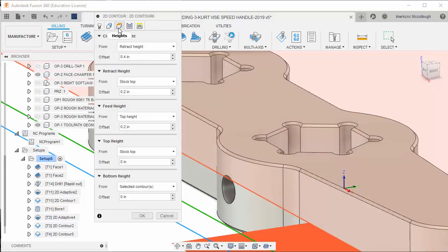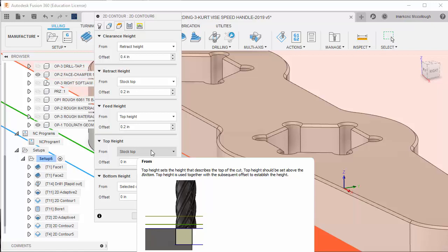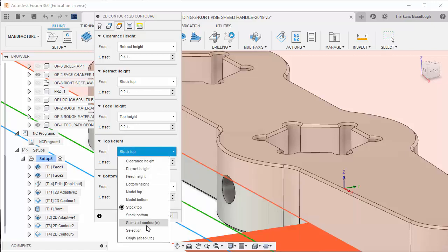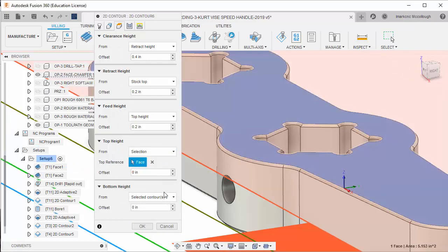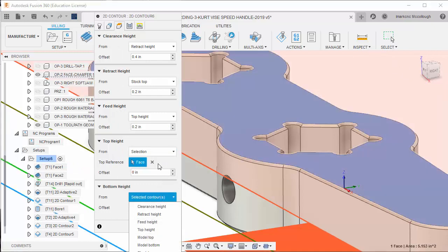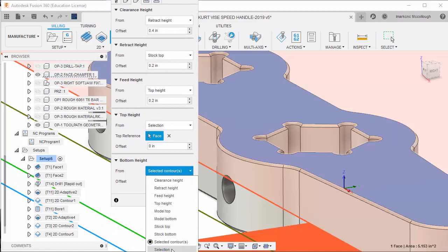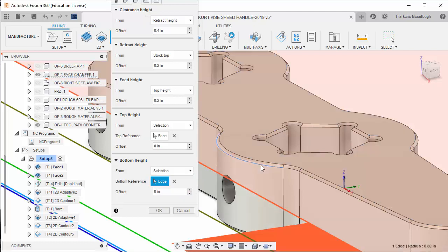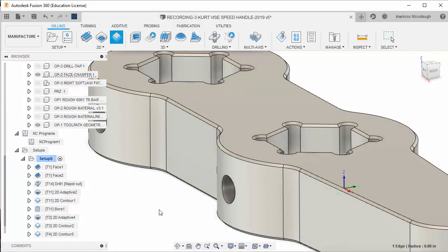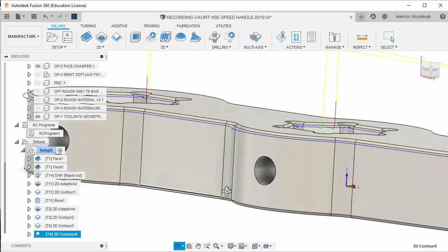From there, the same idea is our height again. Since this is a different level, it's not the same level because they're all cut different in the jaws and where they're positioned, I'm going to choose the selection, grab the model. I'm going to choose my contour selection. Let me move that up a little bit. And I'm going to choose the selection again down here, and I'm going to choose it to there. I'm going to add a -10 thousandths to that one too. And again, that toolpath will come up.